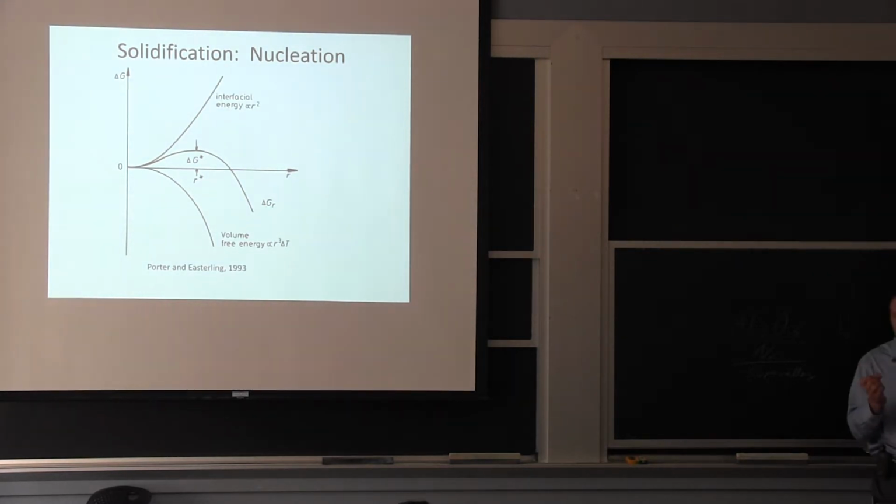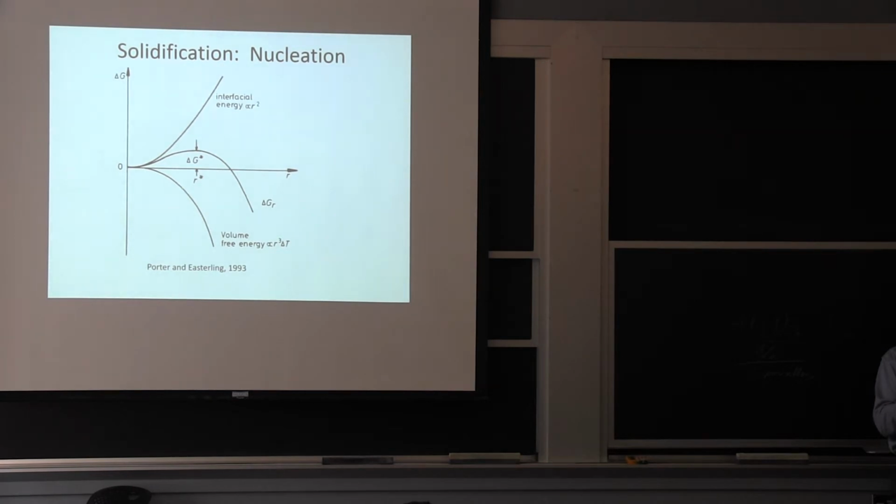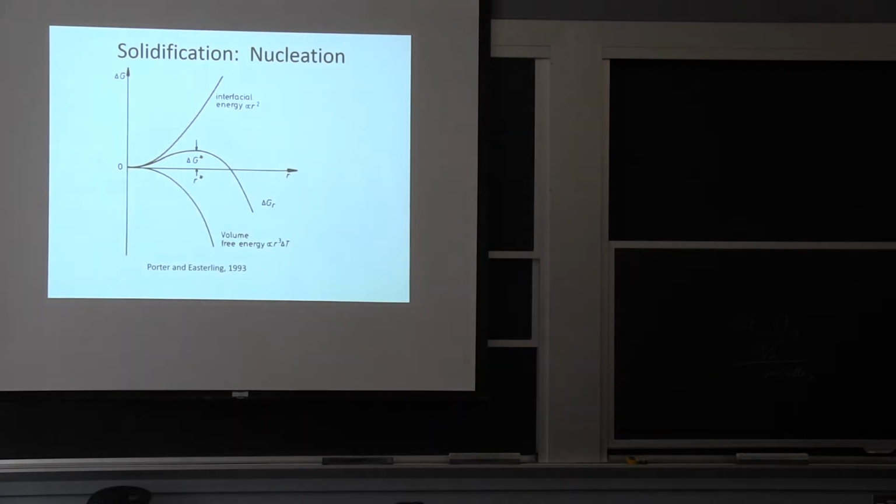If you don't have a mold, if you don't have solidification starting from a surface, you have to wait for hundreds of degrees lower than the fusion temperature to start forming your part. And that's something I know a lot of people get wrong, sometimes like, oh yeah, I'm going to start forming grains everywhere. So no, the grains always form at an interface. It goes from one side to the other, because if you wanted to start forming a grain ahead of the solidification front, you have to be hundreds of degrees cooler than the solidification temperature, and that's very rare.